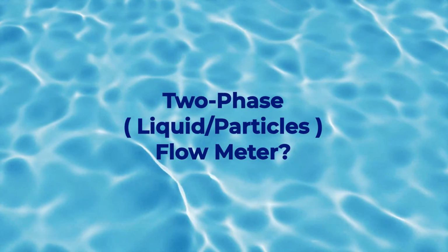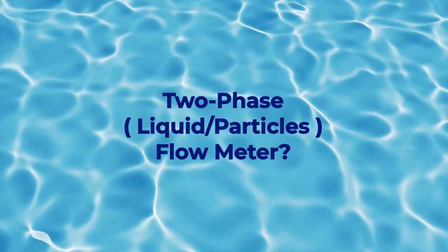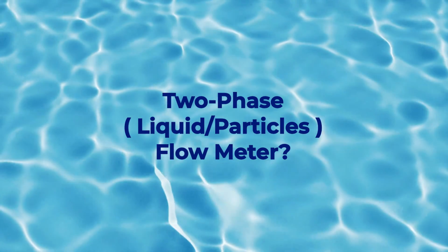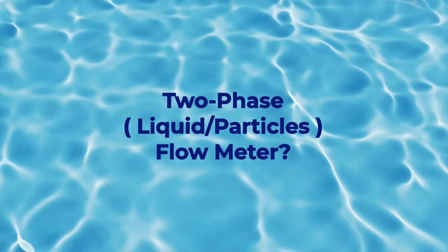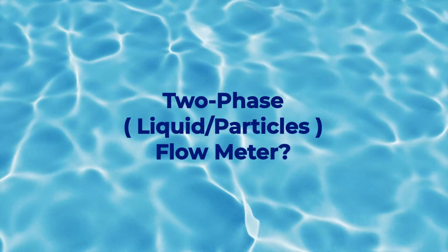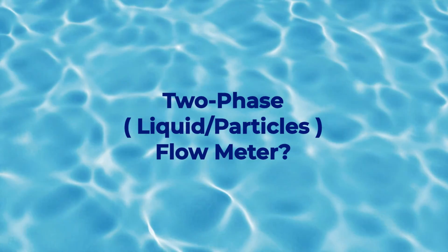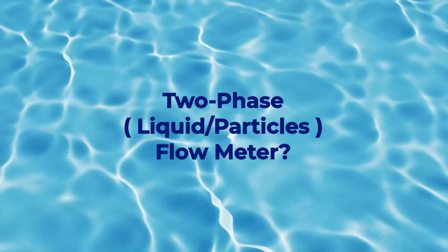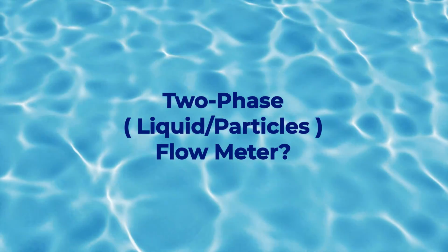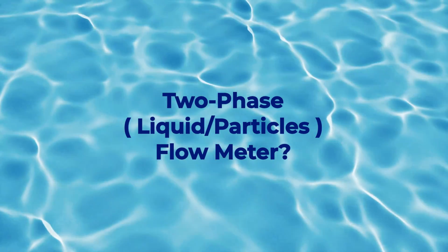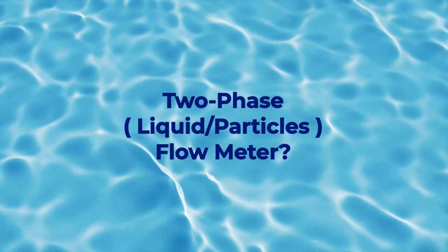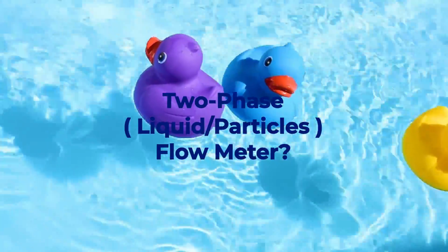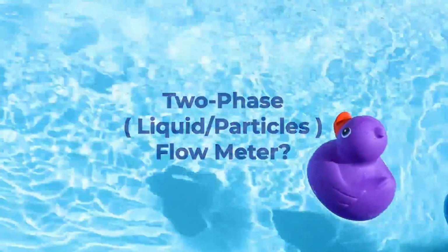What we do though with the mag meter in these applications is we're going to ask you all those questions, and we want to keep the velocity under 10 feet per second. The lower the velocity, the less slurry noise that's created within the flow tube. And then we may also, even though it may not be necessary, stainless steel electrodes are the most common, but in slurry applications, we may put Hastelloy C, the alloy, which is a Hastelloy equivalent, because that has better characteristics for slurry noise. So, we can do it in a mag, no problem. We just, again, would look at the application and make sure we size the meter properly.